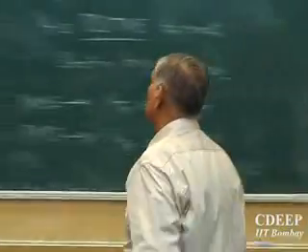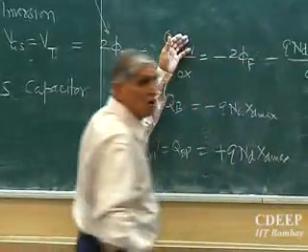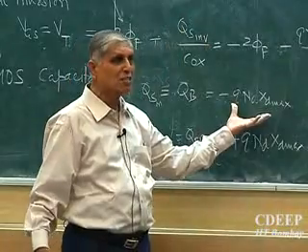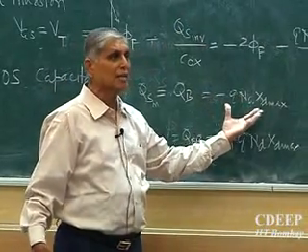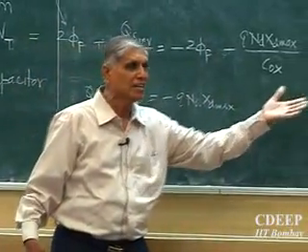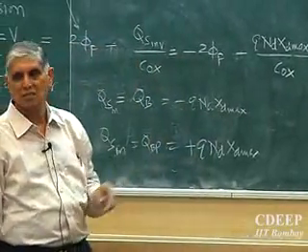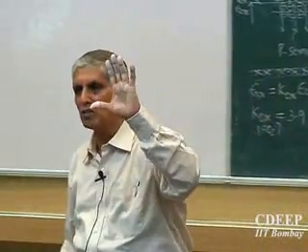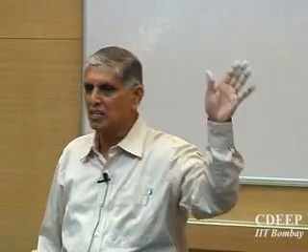This is Gauss's law. So this first minus term appeared because of Gauss's law. But in the case of P substrate, this itself was minus. In the case of N substrate, that is positive, QND, so that sign will become minus. Is that correct? So Vt for a P channel device or PMOS device is always negative. For NMOS devices it is always positive.